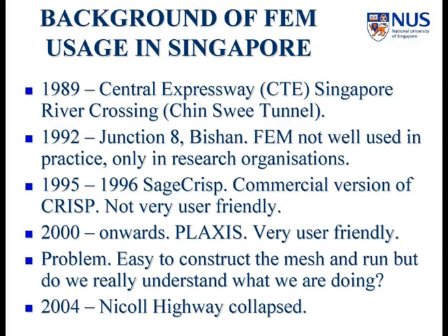There was a tunnel that underpasses the Singapore River, and it was decided to use FEM because in the middle of the excavation, the diaphragm wall actually moved out by something like 200 to 300 millimeters. All right, and the road was declared a danger zone because it was in danger of collapse. Okay, all the curbs buckled up, so it was quite a scary sight.